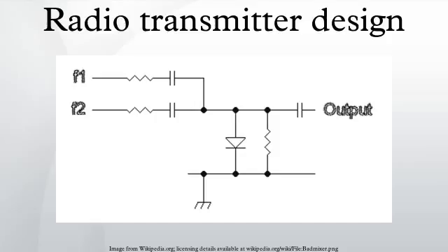Screen AM modulators. Under carrier conditions, the stage will be a simple RF amplifier where the screen voltage is set lower than normal to limit the RF output to about 25% of full power.